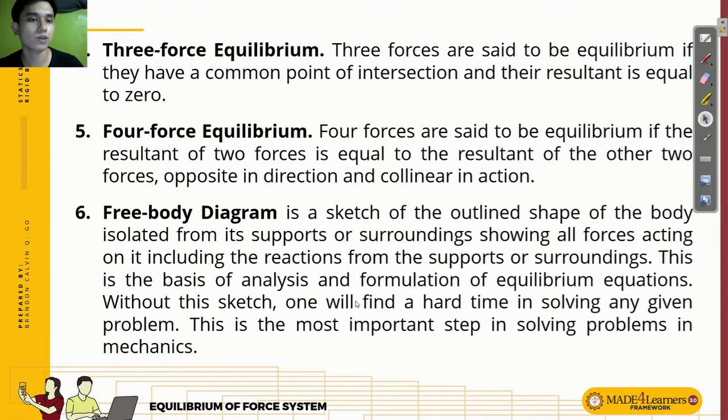Okay, so next, we have the free body diagram. This is the sketch of the outline shape of the body isolated from its supports or surroundings, showing all forces acting on it, including the reactions from the supports or surroundings. This is the basis of analysis and formation of equilibrium equations. Without this sketch, one will find a hard time in solving any given problem. So, it is the most important step in solving problems in mechanics.